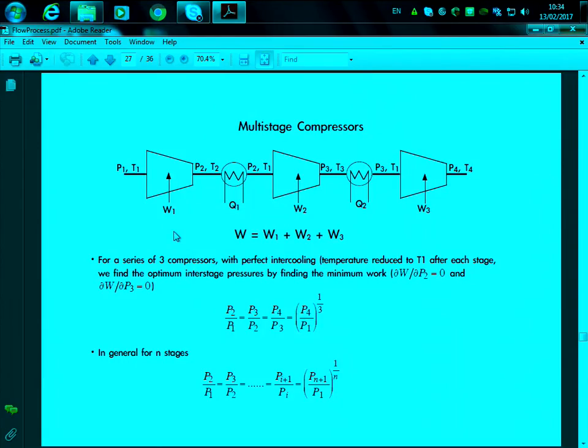Okay, so first of all, we may have the constraint of the fluid properties that we cannot heat to that temperature, so therefore we need this type of compressor. But then again, when we have multi-stage compressors, we can have a higher efficiency than only 1 compressor. So that means that having 3 compressors to get the same pressure will be more efficient. You will lose less work in heat. You will use it more efficiently, but then you will have to use more compressors.